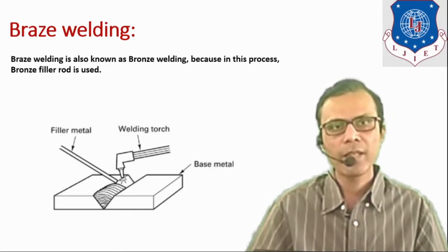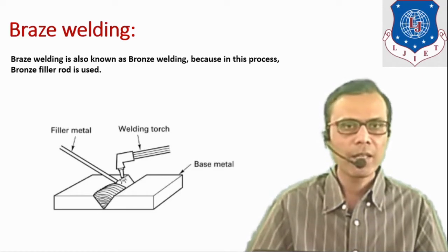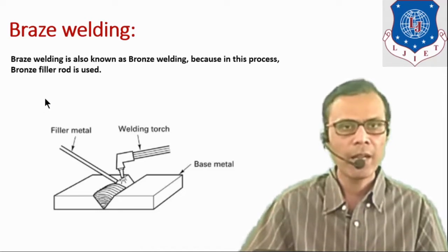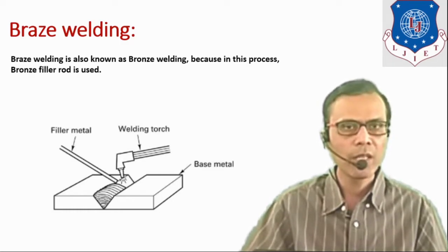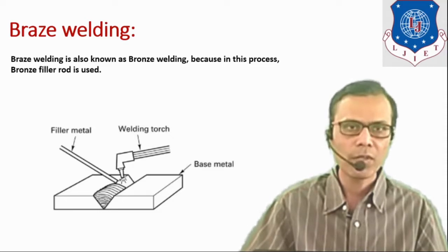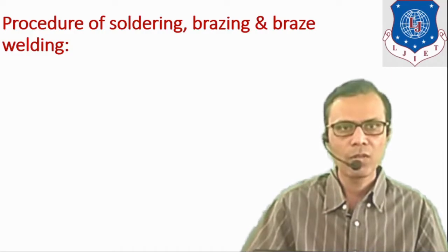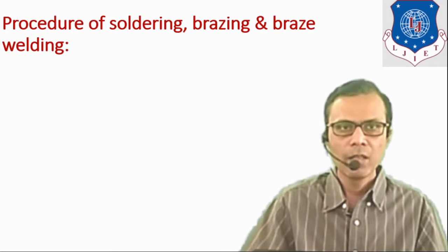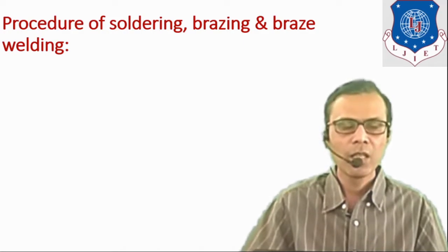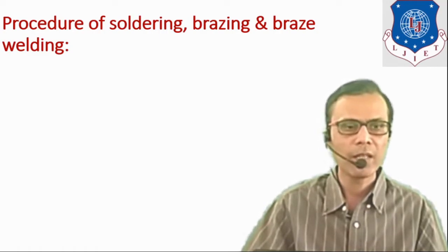Another difference is that the filler material is not deposited by capillary action, but the filler rod is heated and melted and directly deposited at the welding zone, as we do in the case of the welding process. Now let's see the common procedure for soldering, brazing or braze welding. Braze welding is similar to brazing, but the main difference is that here we are using bronze filler metal.